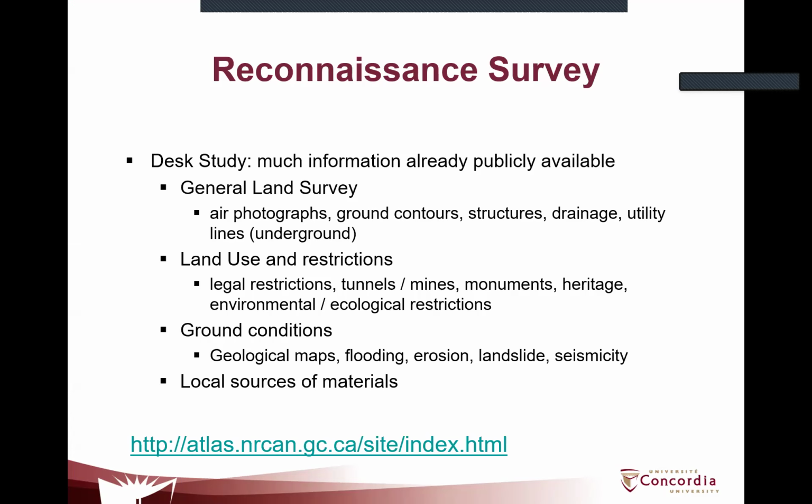So for this, we use air photographs, contours like the ones you did in surveying, and you will also need the location of structures, drainage, utility lines like gas, water, and so on. You need to consider the land use and restrictions. So the type of land uses, if it is just empty land, empty plots, or if you have any residential, industrial, commercial. Also, you need to consider if there's any tunnels, mines, monuments, and heritage sites.